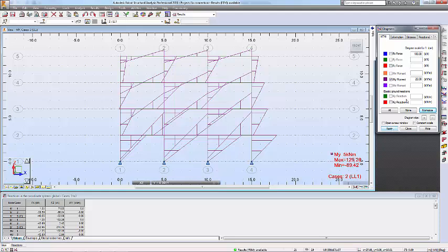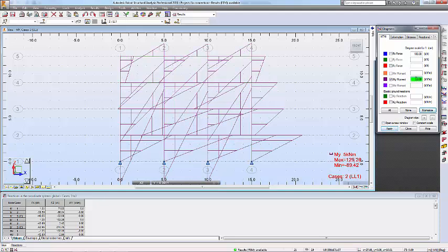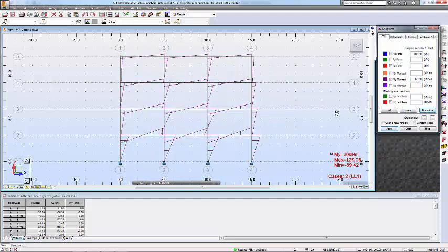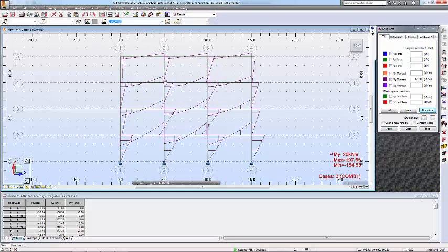So these are the moments you can have. Let's maybe put this one to 10. Hopefully that gives you a better view. Oh, 10 was too big, so let's put in 60 and apply this one. So that's maybe a better view for the lateral load. So when you have a lateral load, you see how the bending moment distributes inside the structure. And then this is the combined effect. You see this curve is caused by the uniform distributed load in the middle. So that's what we did last time.